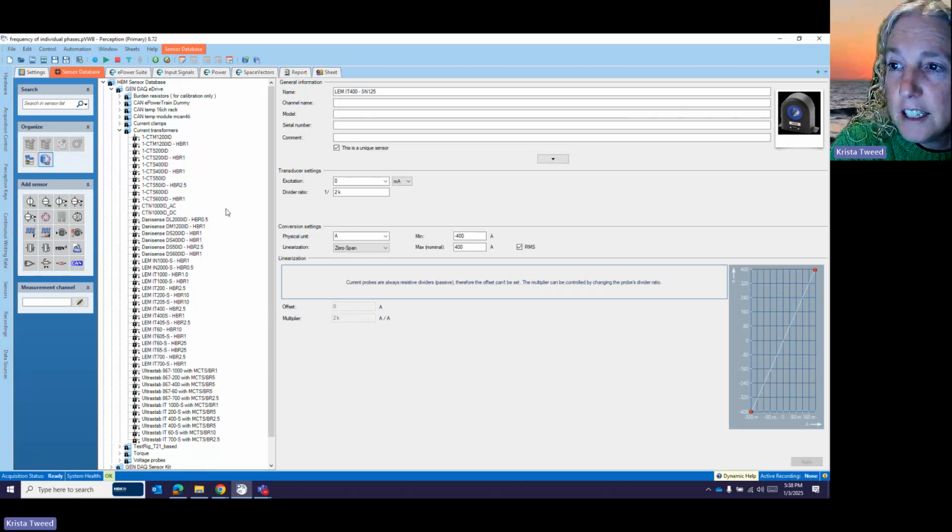You're going to see two different types of sensors here in the database. You can notice at the top, we've got our HBM current transducers. We partner with DaniSense on those. But you see there's a double entry for each kind. Why is that? Well, we have two different modules that can be used in the eDrive Power Analyzer to make current measurements. Our original module was the GN610B, which has 6 voltage input channels,